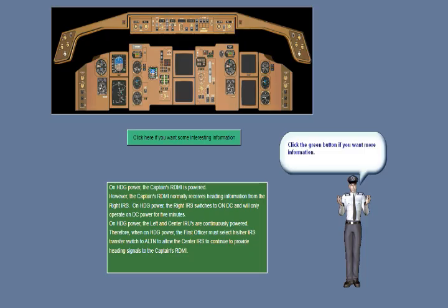Before we finish our APU generator discussion, let's discuss an APU generator fault indication. With the APU control switch in on and APU running, the off light, in combination with an ICAS advisory message of APU generator off, indicates an APU generator fault.